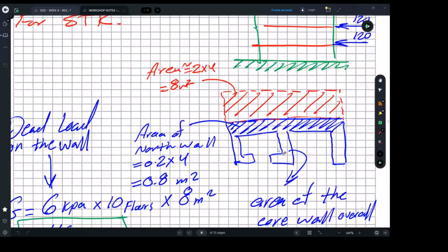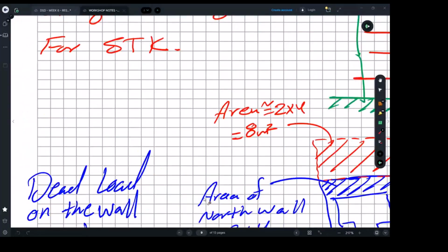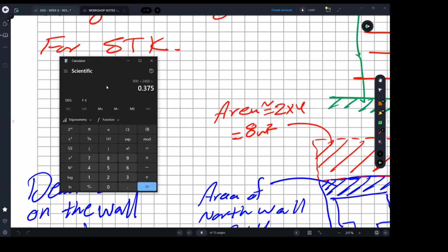So for your case, what was the area? It's 8.3. The hatched area, the supported area, is 8.3 something. That's fine. So 8.3, and so what you're going to have is 8.3 multiplied by the thickness, multiplied by the density. That's from one floor, right? Yes. And for 10 concrete floors, it will be 415. That's only the slab. And I think that's why I was showing here.